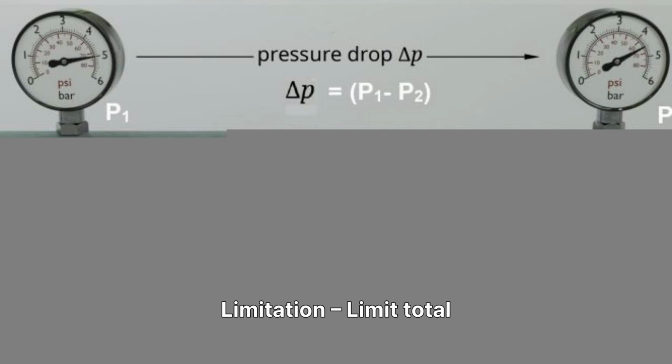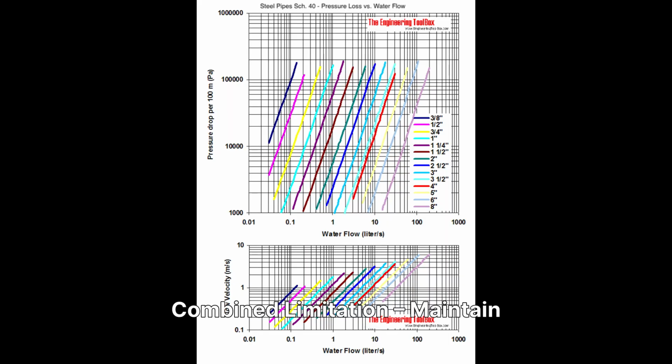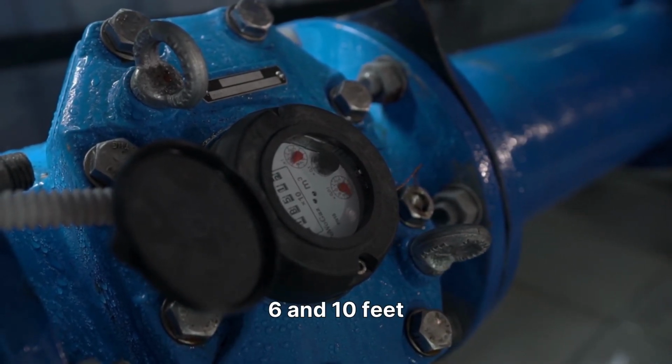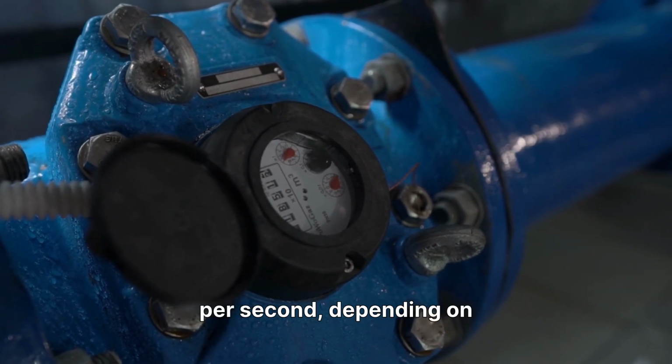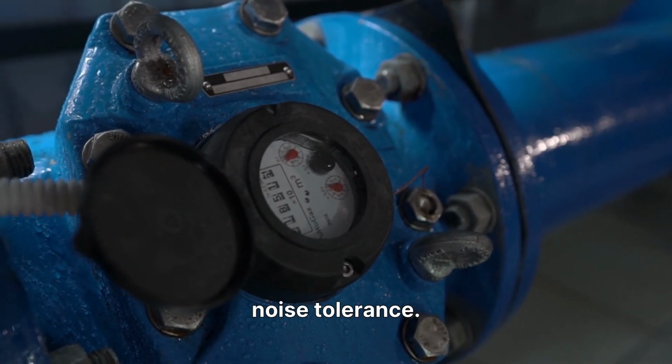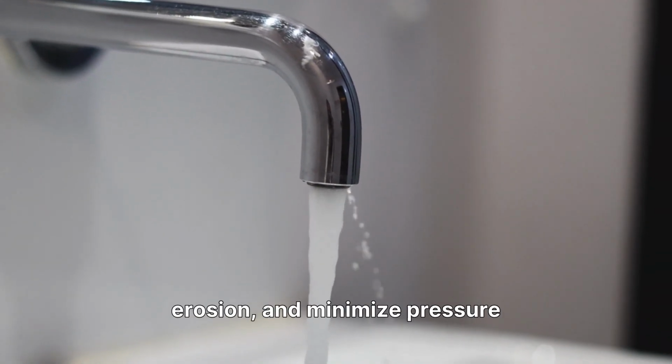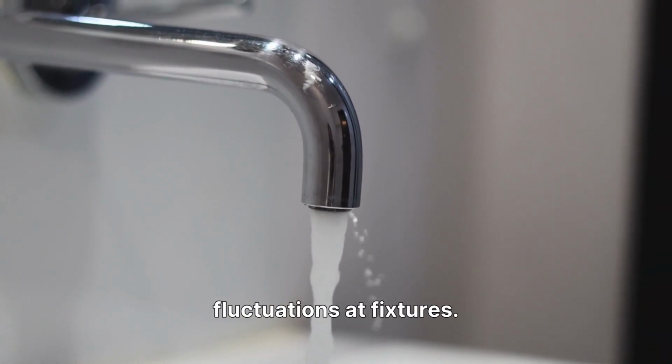Pressure drop limitation: limit total friction loss to 5 psi per 100 feet of pipe. Combine limitation: maintain the same 5 psi per 100 feet while keeping velocity below 8 feet per second. Velocity-only limitation: restrict water speed to between 6 and 10 feet per second, depending on the pipe material and noise tolerance. These limits help maintain steady flow, prevent pipe erosion, and minimize pressure fluctuations at fixtures.